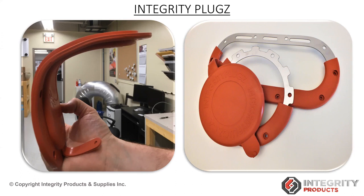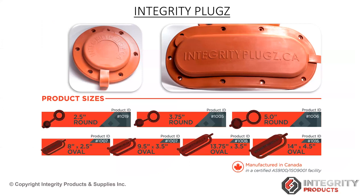We use an 18 gauge steel for the metal, and in our manufacturing process, the silicone is poured at a very specific rate at a specific temperature, and then allowed to cool along the right time frame so that the silicone actually bonds to the metal. So this helps spread the load of the bend and the curvature. You're not going to get any kinking of the metal or metal fatigue at one particular spot.